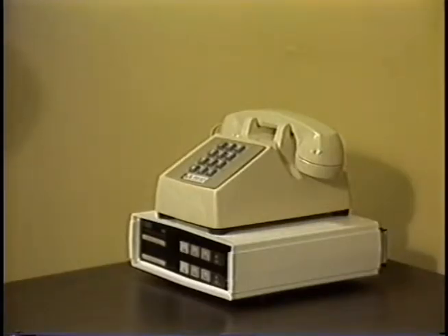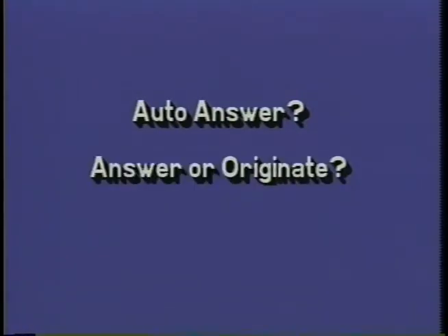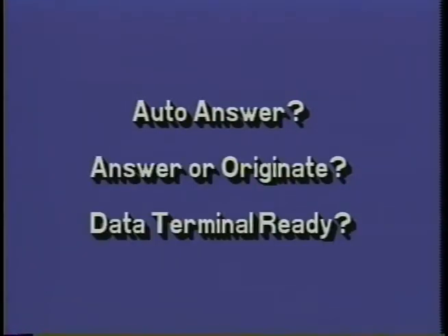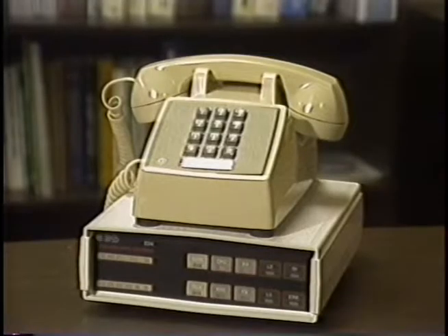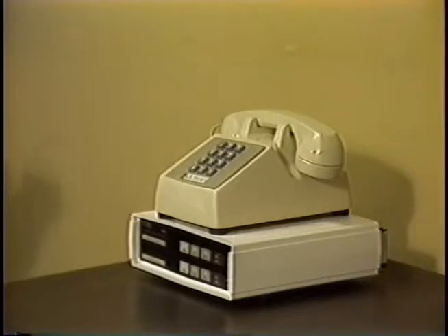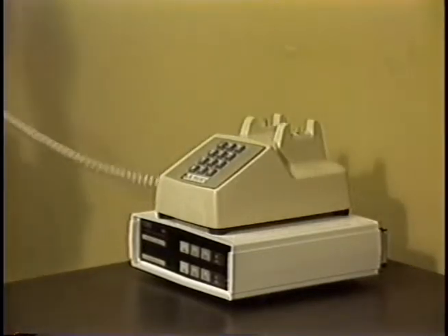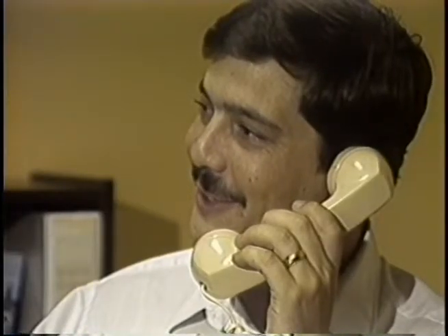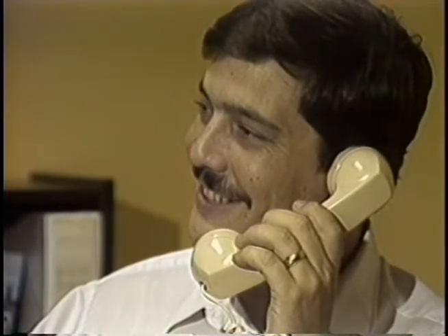At the computer end, there are a couple of important answering modem options. These are typically limited to auto-answer, answer or originate mode, data terminal ready from the terminal, or forced on in the modem. The auto-answer feature must be on, of course, for an unattended modem at the computer. If, on the other hand, incoming calls will include both voice and data, the auto-answer feature should be turned off so your flesh and blood callers get you, not the modem.